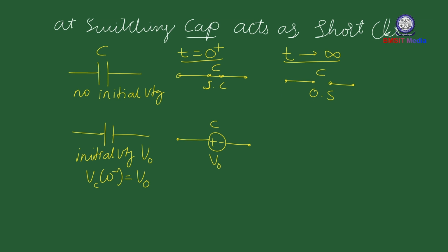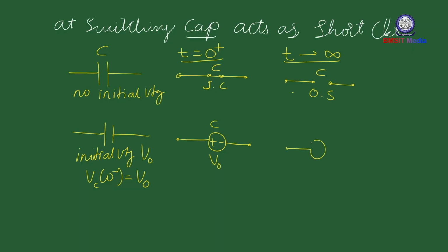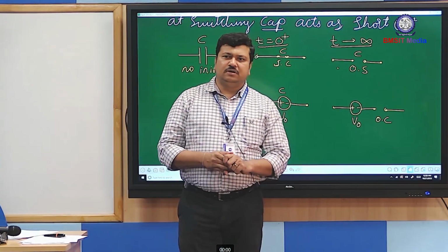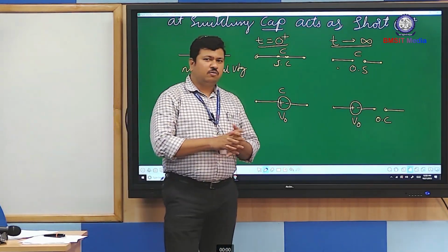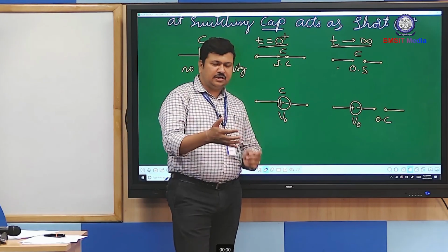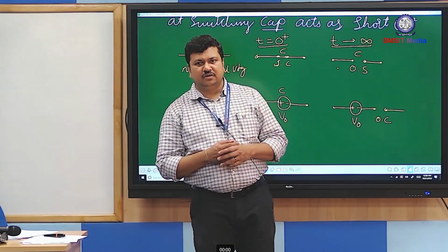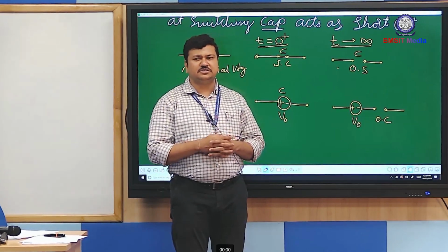Now at steady state condition, the capacitor acts like a voltage source of the same value V0 in series with an open circuit. So this is about the analysis of capacitor and inductor with their initial conditions. What we have observed in basic electrical engineering through mathematical expressions using the phasor relations, the same thing we have observed here in different terms, but concluding the same behavior of the capacitor and inductor.